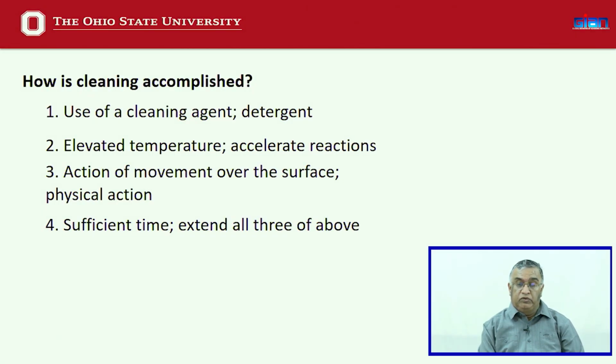So what do you do for cleaning? Basically, you use a cleaning agent, oftentimes a detergent with water, so that you are able to clean the surface. Second, oftentimes you can clean this by pumping water at room temperature, but things will be much more effective if you do this at a relatively warmer temperature, say 60 or 70 Celsius, depending on the operation.